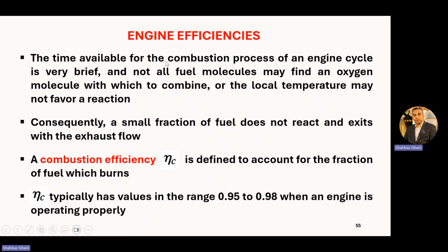The time available for the combustion process of an engine cycle is very brief, and not all fuel molecules may find an oxygen molecule with which to combine, or the local temperature may not favor a reaction. So the explanation is that combustion occurs over a very, very small time period, in which all the fuel molecules may not find oxygen molecules to react with.